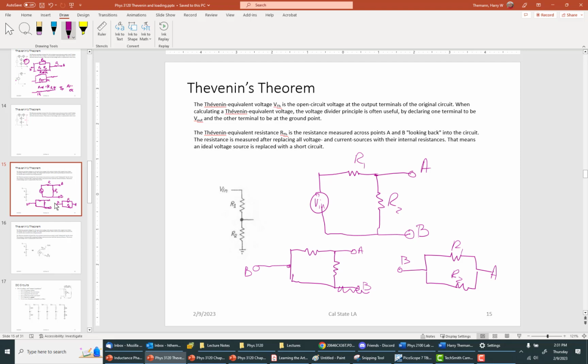And I can just let this wire stretch a little bit and shrink this wire, and then I come to that. And now you see how R1 and R2 add in parallel. I haven't proved it, but I've shown you that I've got this Thevenin decomposition that I know works, and when I apply the strict rules of Thevenin, you see how R1 adds in parallel with R2. It's counterintuitive because R1 is attached to the voltage supply and R2 is attached to ground. But of course it is much easier when you draw it this way.